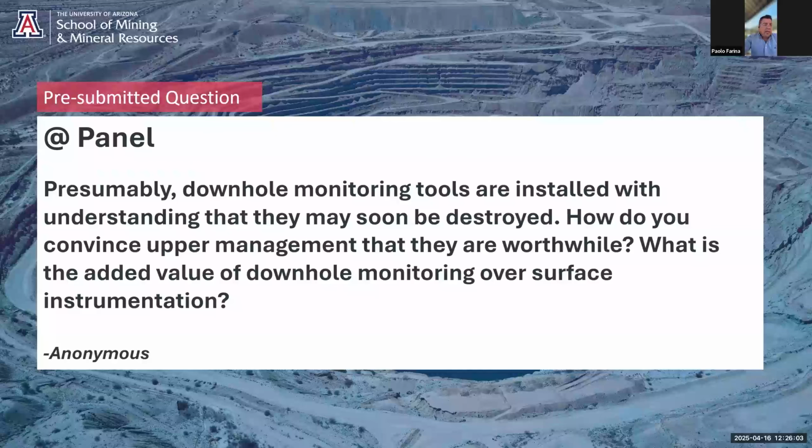Another example, and then I stop talking, is when you look, for example, at instabilities on stockpiles, on waste dumps, whatever. Those types of assets are typically moving. They are supposed to move because they may have subsidence, settlements. So to have movement at the surface could be not enough to say that we are having a critical situation potentially developing. So you need to verify, first of all, the mechanism, the depth, and what is the triggering factor.